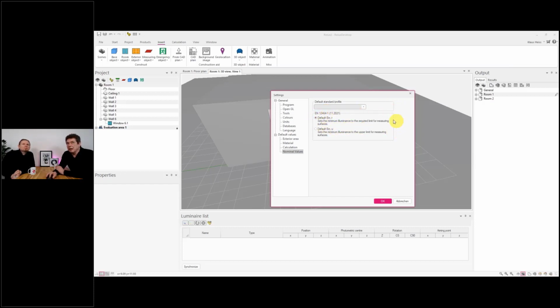Also, you have this option, the standard option, which allows you, according to the new 12464, to choose the illuminance level related to the profile you have chosen. Or you say no, I want all the time the greatest value inside of it. It's a little bit discussable. You will be asked with a pop-up on any setting. I'm sure you have seen it in the past, but here is the option to set it once for all to the lower or to the upper value. If you select in the pop-up never show me this again, then you can here switch between the two extremes.